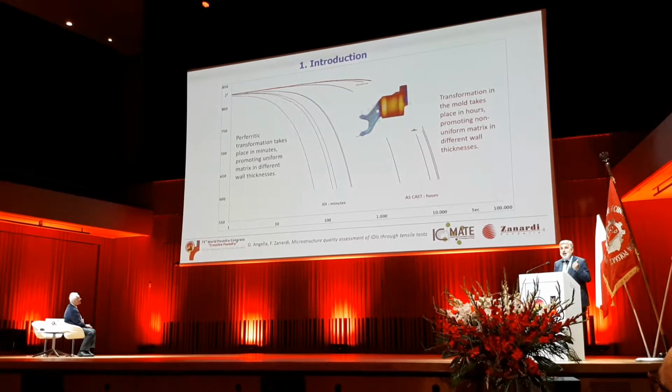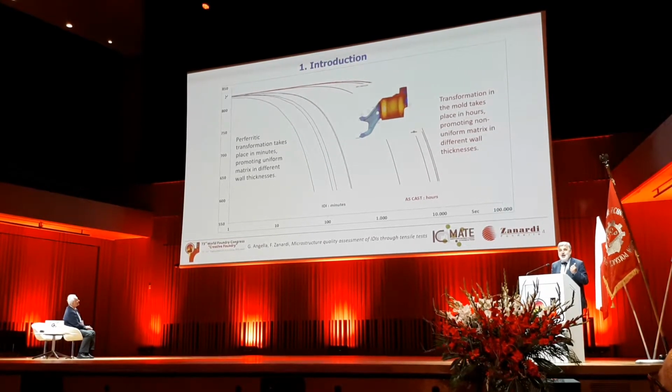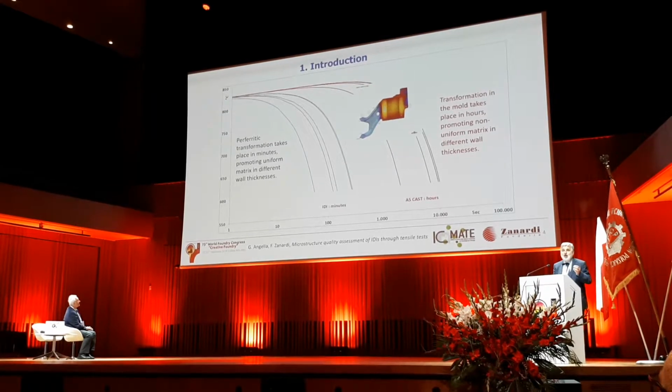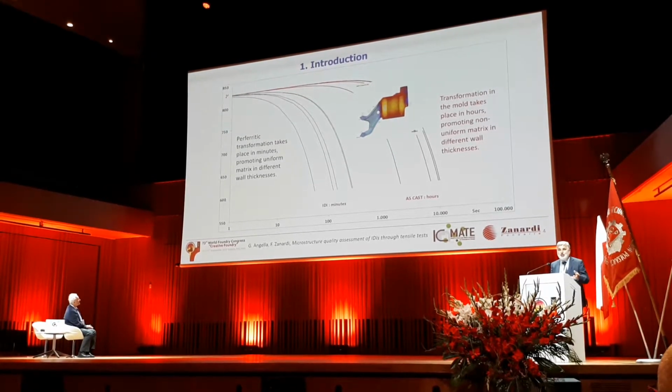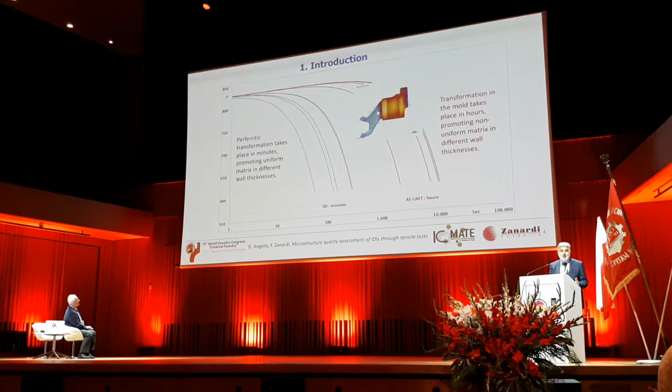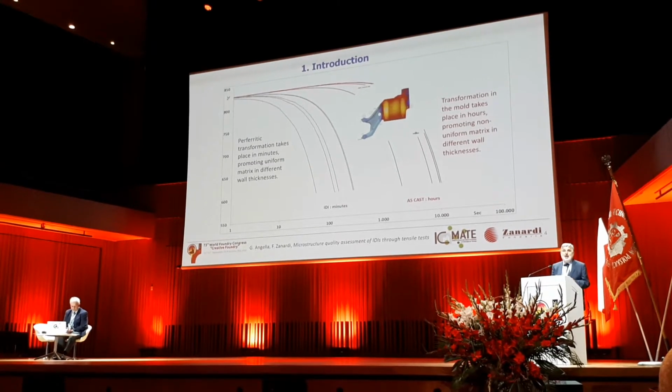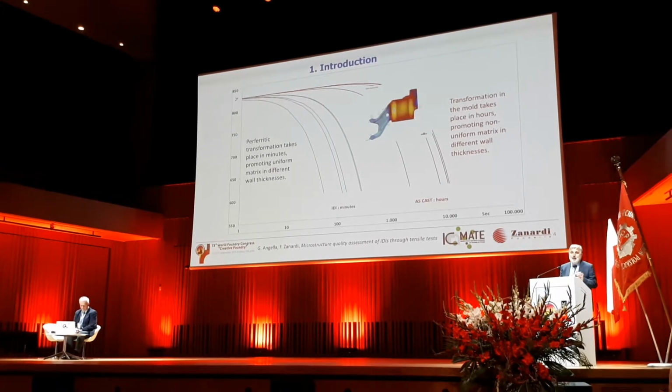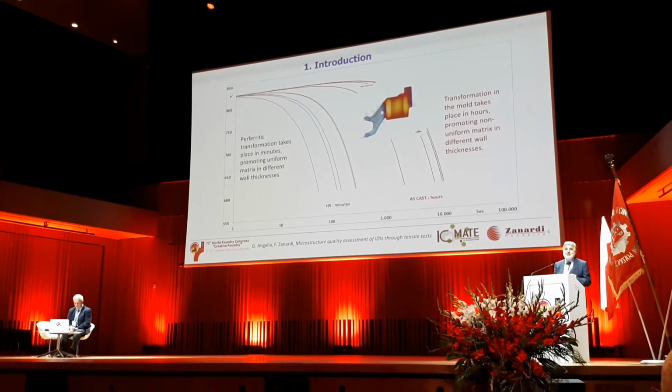So, first of all, we have no segregation, except silicon, in a eutectic when we have the solidification, and we have not a mobility of carbon during the eutectic transformation, so the ferritic transformation happens in situ.